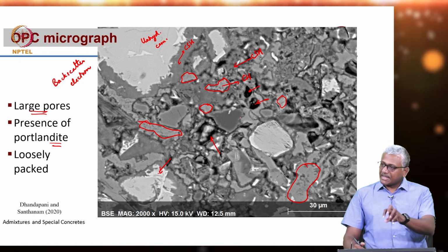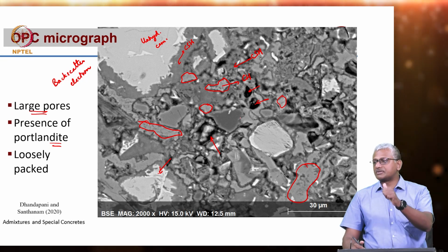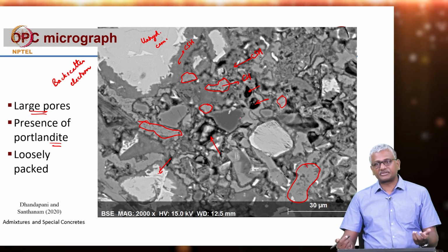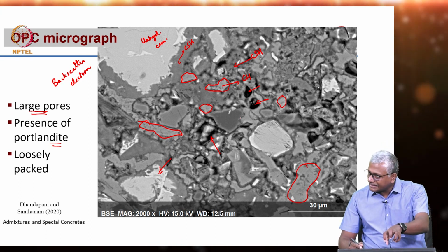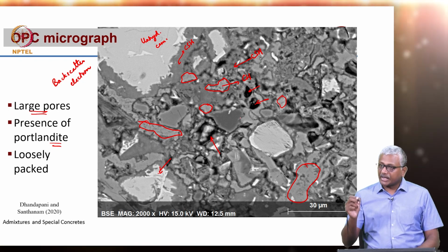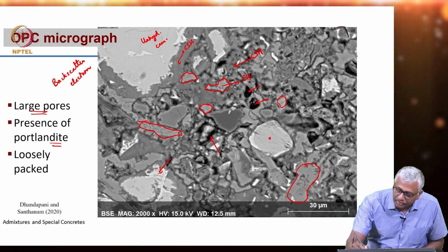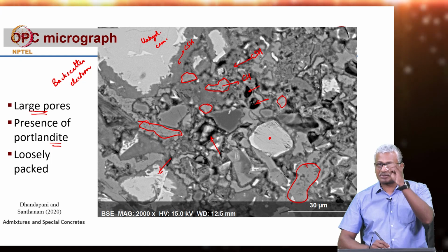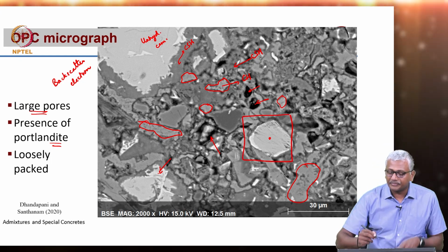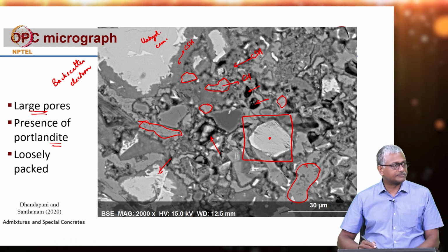So, if there is a calcium atom present in your system, you will get calcium X-rays, silicon will show silicon X-rays, aluminum will show aluminum X-rays and so on. So, you can actually collect the X-rays that are coming out of the object. For instance, you can shine the electron beam right on a spot and collect the X-rays from that spot, or you can shine the electron beam across an area and collect the X-rays from an area.